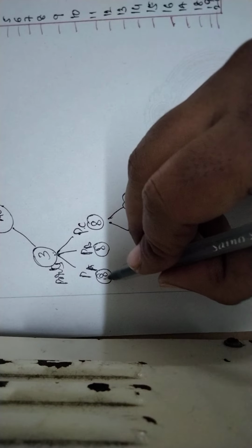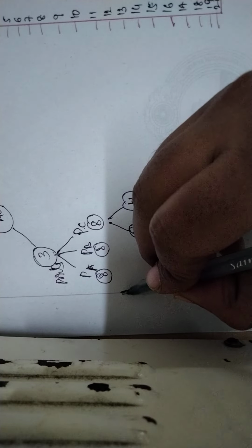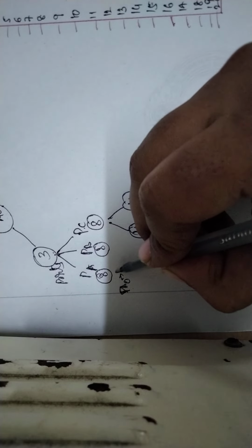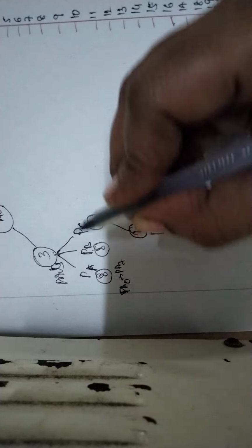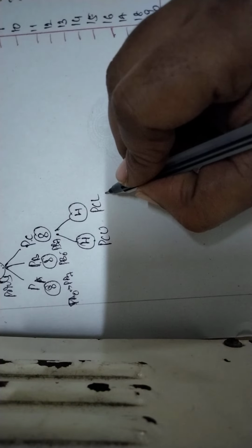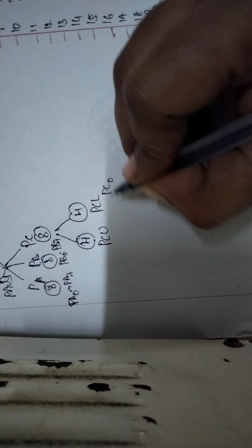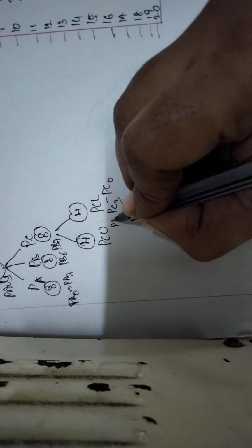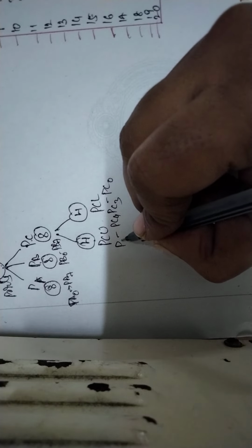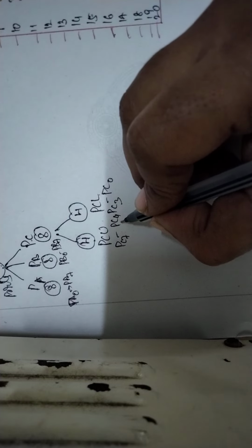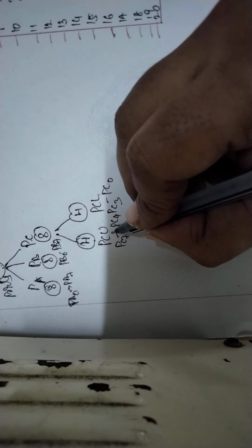Actually, port A consists of port A0 to port A7, port B also has port B0 to port B7, and port C has C0 to C3 and port C4 to C7. Pins 0 to 3 are the port C lower part and pins 4 to 7 are the port C upper part.